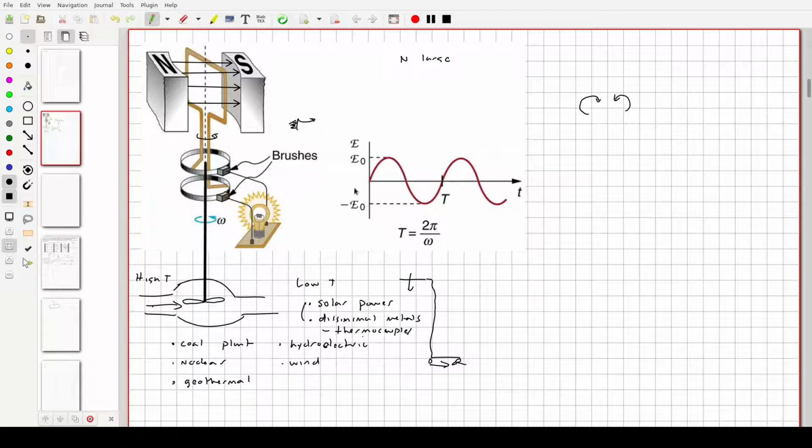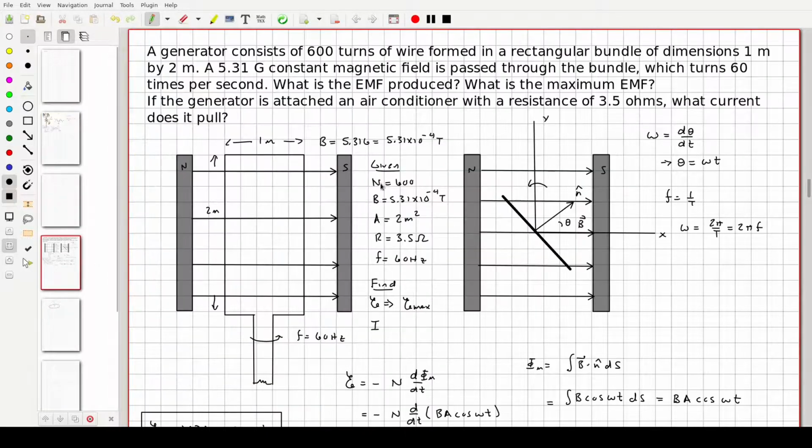Okay. Now there is a name for this type of electrical circuit. There's a name for this type of current. It is called alternating current, AC current, and this is what your house uses. Electrical devices in the United States and in the rest of the world are generally designed, if you're going to be using a house, to run off of AC, or at some point convert AC to DC, like for example with respect to your laptop when you charge it. In a house in the United States, the electrical current oscillates back and forth 60 times a second, at 60 hertz. Okay.